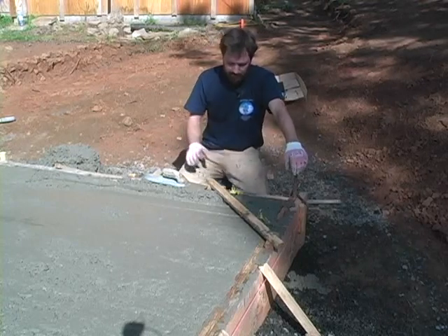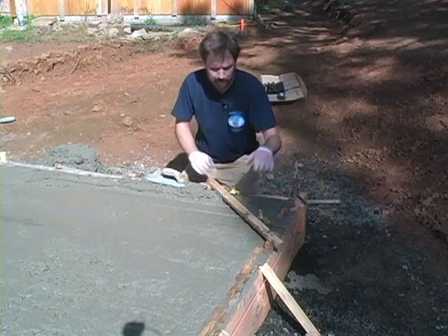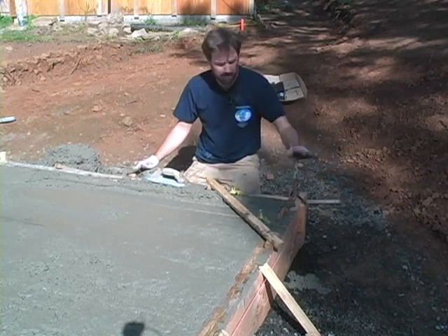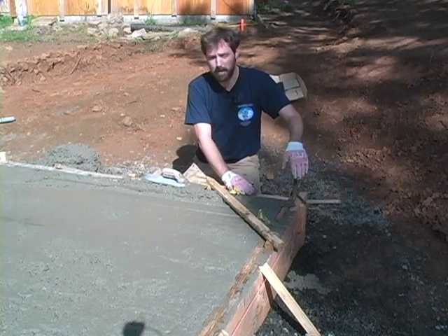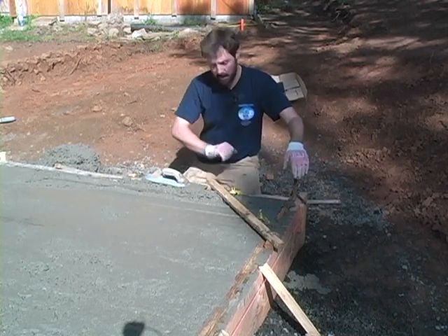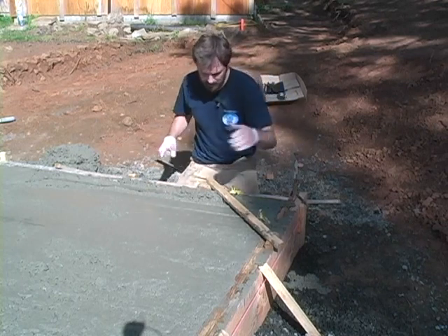Now once you've screeded everything, you can make sure that your corners are square and put your brace back in place if you need to. Now with all the bracing we've got here and the corners marked off, your corners may have stayed square during that pour with no problem, in which case you can take the braces off to trowel out and then replace them when you're done. So basically what we've done is we got the screed board down through here,